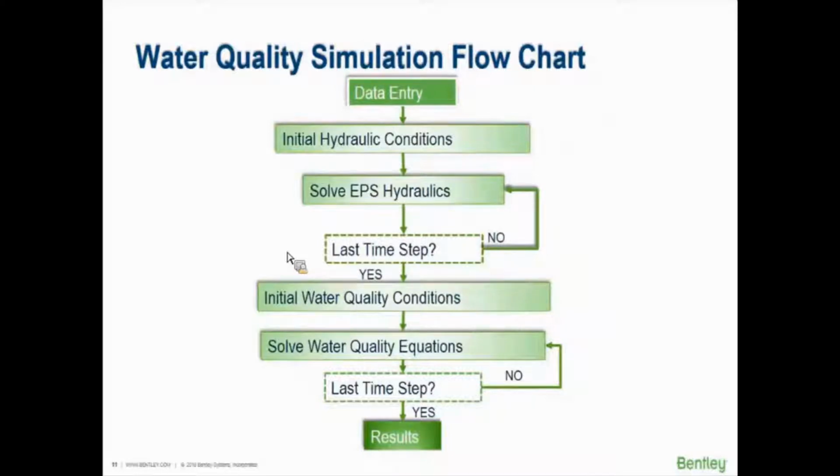Basically, you start off with the data entry, and we've been talking over the past in the fundamentals course, and then during this past few days, we've been talking about data entry and how to get it into the model. Once you have your initial hydraulic conditions set up, you solve that model, so you would compute it as an extended period simulation, and then it's going to generate data for every time step. Once the controls reach the end of the time step, great, you've got all of these snapshots in time, and then the initial water quality conditions are entered.